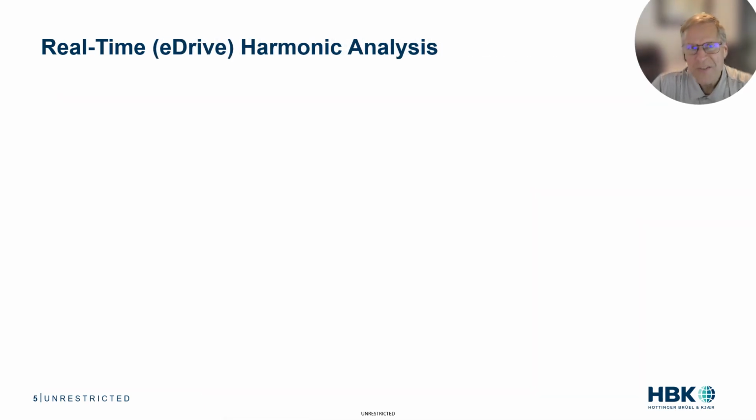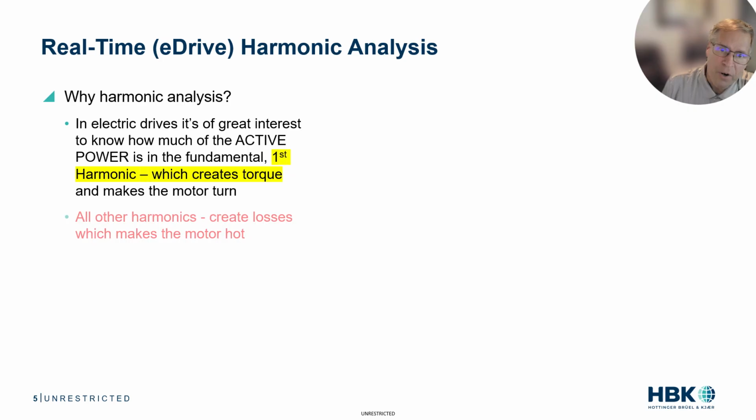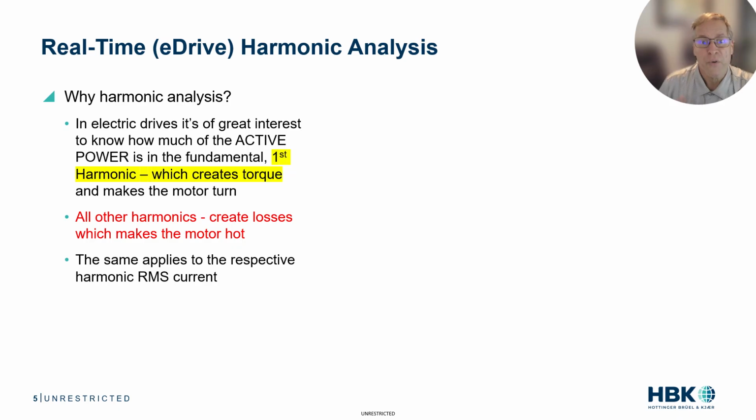Now let's talk about harmonic analysis for applications like electric drives. So why harmonic analysis? In electric drives, it's of great interest to know how much of the active power is in the fundamental. Generally, the first harmonic creates torque, which makes the motor turn, and often the other harmonics create losses, which make the motor hot. The same applies to the respective harmonic RMS current.